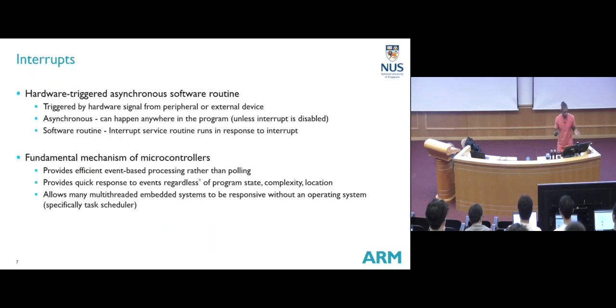Again, why we want to use interrupts is because they are the most efficient way of handling asynchronous events, and I can have a separate code that will execute as and when the event happens. And again, it actually is a way of multitasking, correct? The interrupt mechanism we have actually allows multitasking, even without an OS, but again, we are limited.